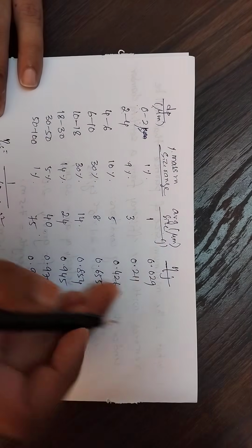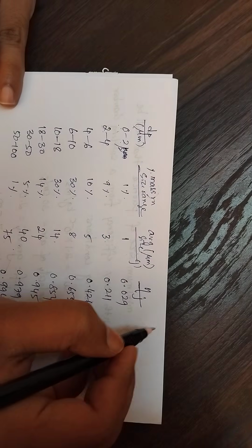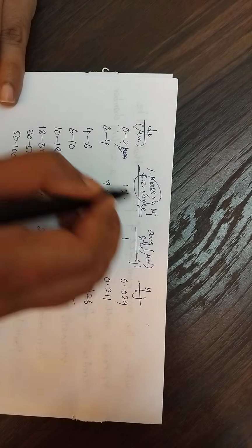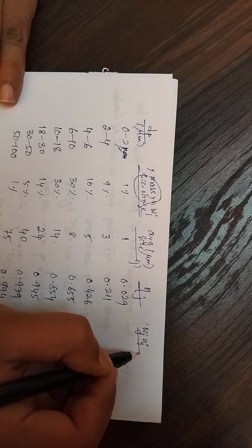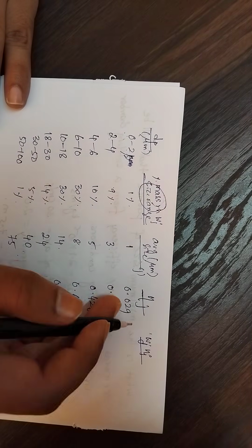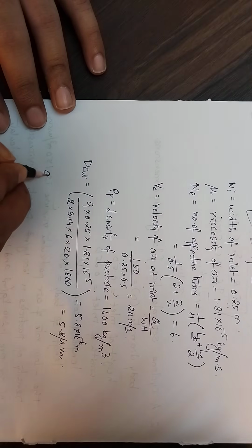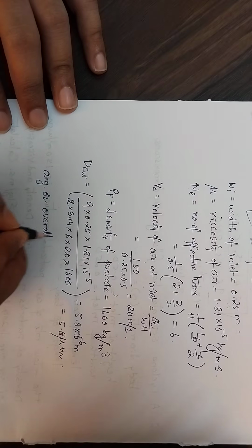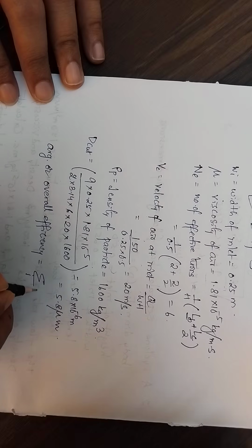What we have to do is take an average weighted by the mass fraction. That is, we have to calculate the mass fraction. Let's call this W_j, mass fraction. Then we just have to multiply W_j into eta_j. Then we have to take a summation. So what we have to calculate is the average, or you can say overall efficiency, which is equal to the summation over j of W_j and eta_j.